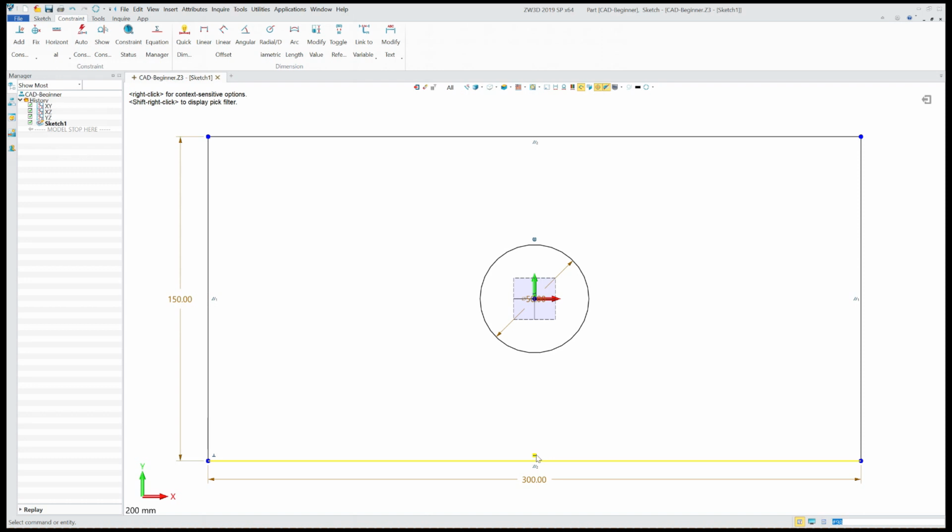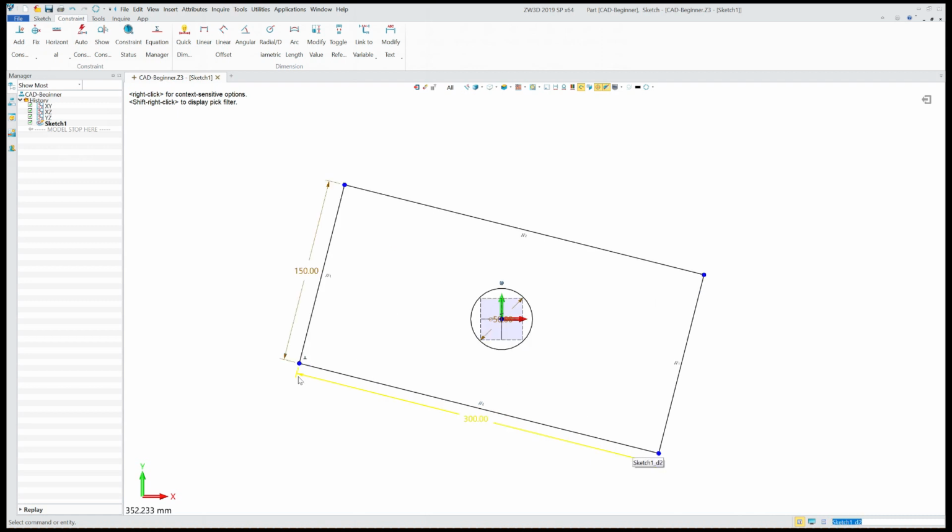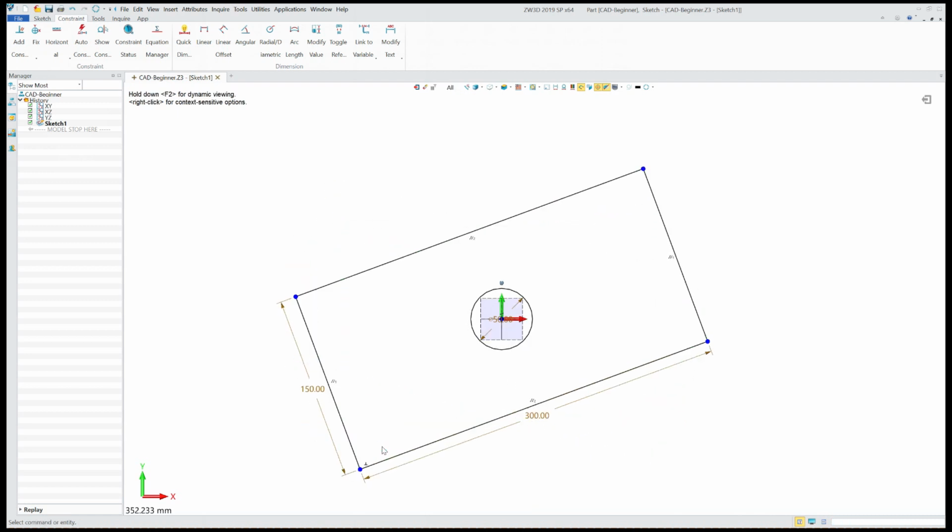the x-axis in this case, because in this sketch plane the x-axis represents the horizontal axis and the y-axis represents the vertical axis. So let's delete this constraint and see what happens. We do that by clicking on it and pressing on delete. And now you can see that we are free to rotate the entities. But notice that the sketch entities still stay correct to one another. That's because we still have some constraints between them.